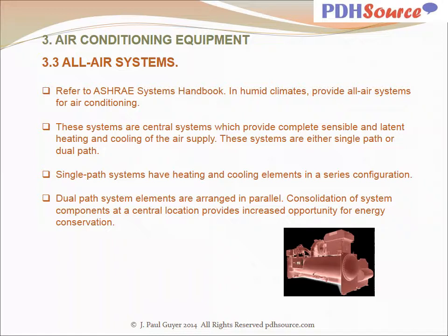Single path systems have heating and cooling elements in a series configuration. Dual path system elements are arranged in parallel. Consolidation of system components at a central location provides increased opportunity for energy conservation.